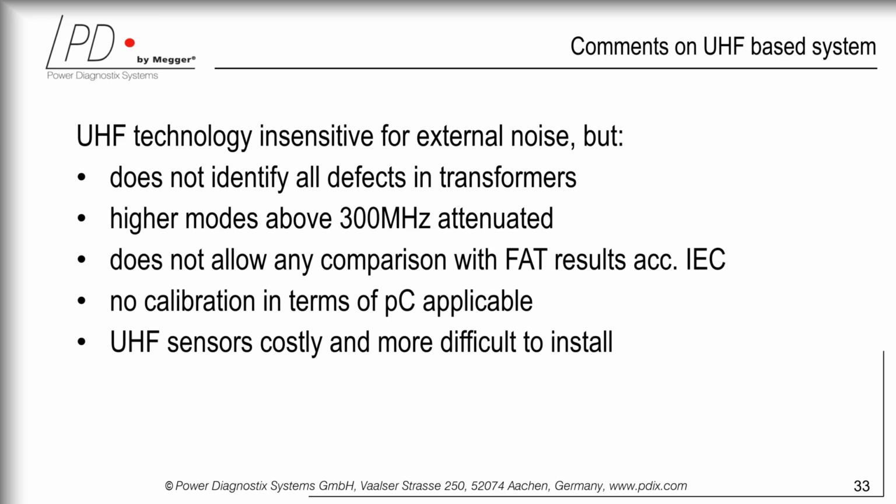Now, some comments on the UHF system. There are lots of UHF systems out there, and I have to tell you that UHF systems are a bit insensitive to certain problems. I mean, they do not identify all the defects in the transformer. There are higher modes above the 300 megahertz, which are being attenuated. Sometimes it does not allow comparison with the factory acceptance tests, for instance, in relationship to IEC modes.